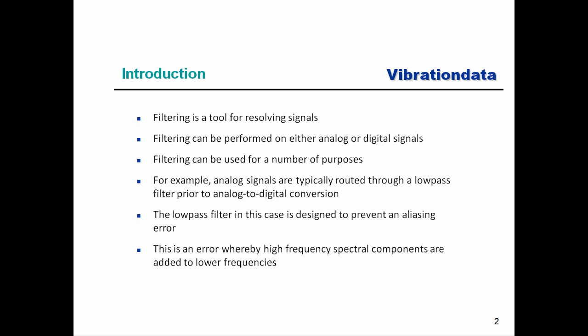But I will say quickly that the cutoff frequency for the analog low-pass filter should be less than 1/2 of the sample rate frequency. And again, specific rules of thumb are available in the previous webinar unit that discussed sampling, the Nyquist frequencies and aliasing.